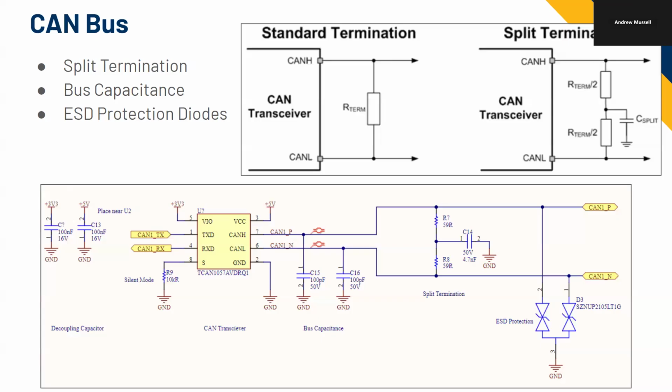So you want to make sure the ESD protection is sized right. It's really meant for when you touch it, if you have electric shock and you feel like, oh, that just zapped me. That can actually be in the range of 16 kilovolts. So this will definitely short that. That's what it's mostly for. But then on the lower end, you also want to size it for if your low voltage bus got connected to communication.